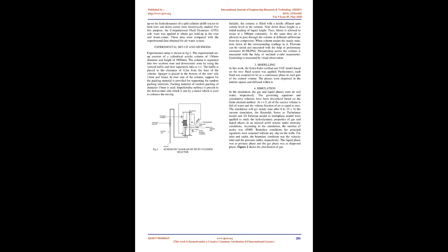regimes, and mixing time. The circulation velocity of liquids is increased by increasing the ratio of geometrical parameters, i.e. liquid height to diameter, when it is more than 10, and it increases the heat and mass transfer rate in the reactor by increasing the oxygen residence time. The initial rise in the gas holdup with increase in viscosity inside internal loop airlift bioreactors has been related to the lower bubble rise velocity, which leads to higher bubble residence time in the riser and a greater entrapment of the bubbles into the downcomer.